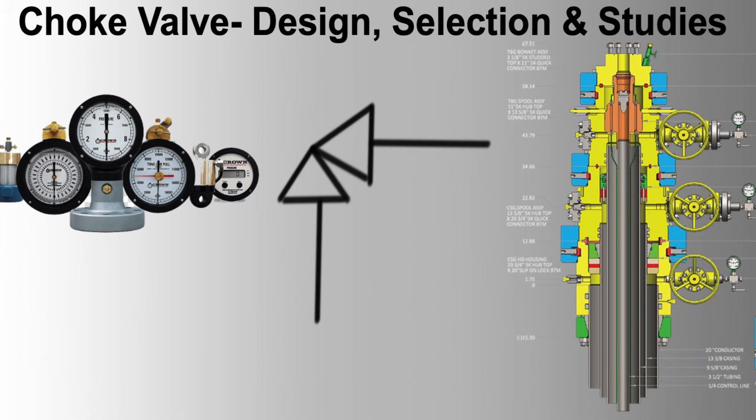5. Actuator malfunction. Problem: actuator failure leading to loss of valve control. Solution: use reliable, high-performance actuators with regular maintenance schedules. Implement redundant actuators and manual override options.